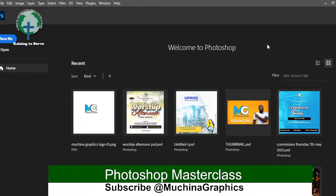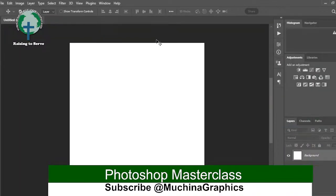So for you to ensure that you have a quality design when you share it, ensure that you have the exact artboard size. So with that, I'm going to click 1080 by 1080, then I'm going to click create. After that, I'm going to be inserting the images that I intend to use. So I'm just going to click file. But before that, let me take you through the interface so quickly.